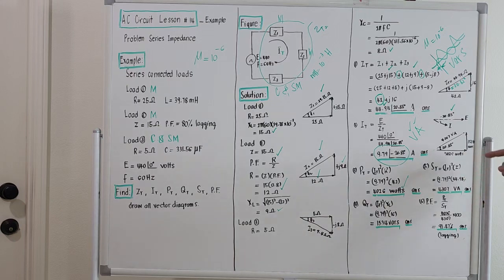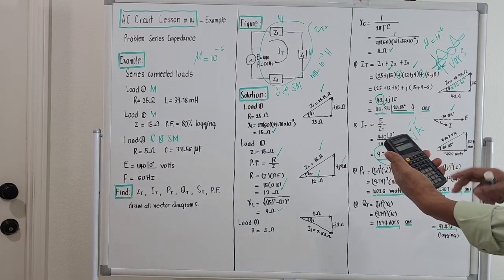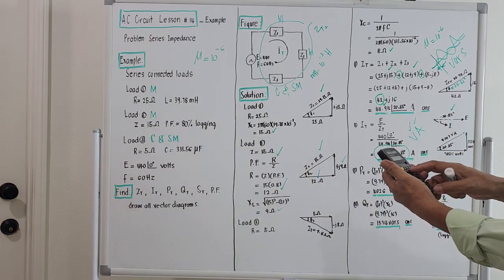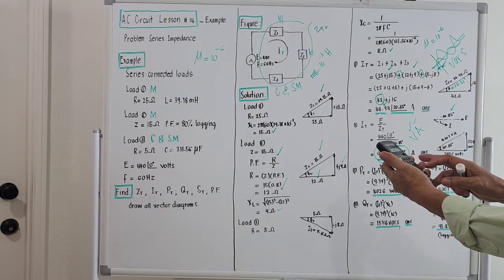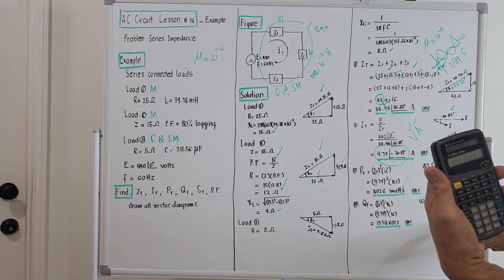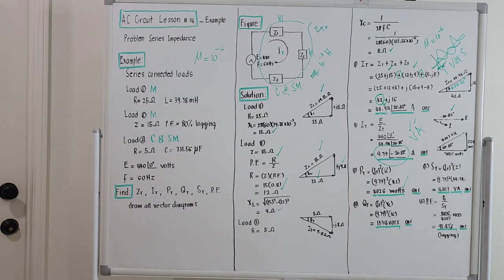Actually, the other solution is that the cosine of the angle between the applied voltage and current, take the cosine, will still be the power factor. So the angle between the voltage and current is actually 20.85 degrees. And one of the definitions of power factor is the cosine of the angle between these two here. We will take the cosine. This is multiplied by 100%. What comes out is 93.45, same as this one. Or 93.47. Okay? Oh, that's it.